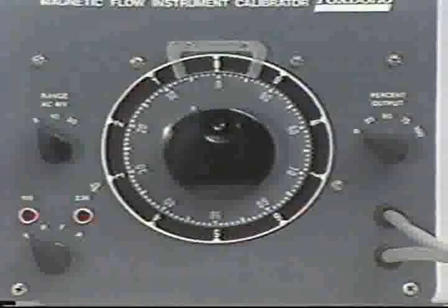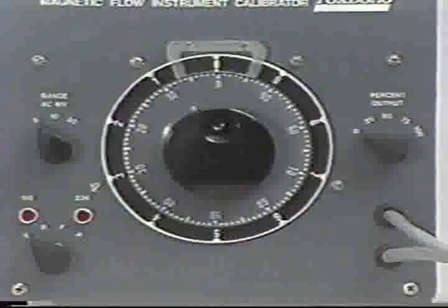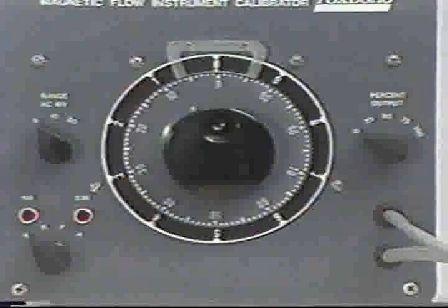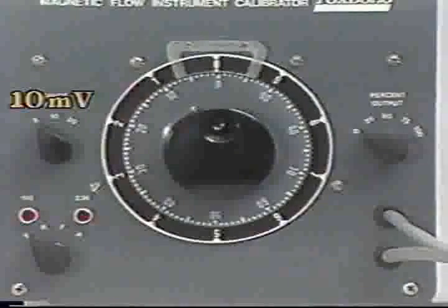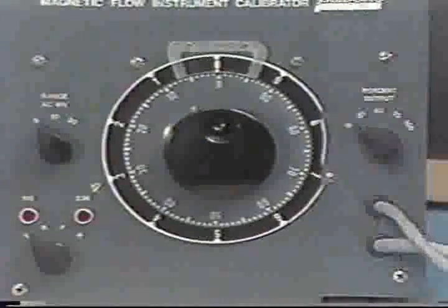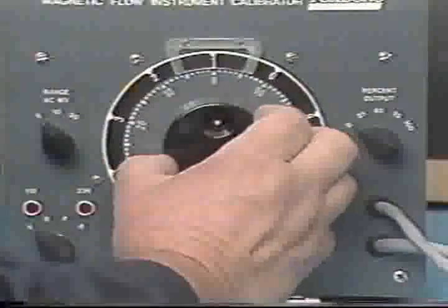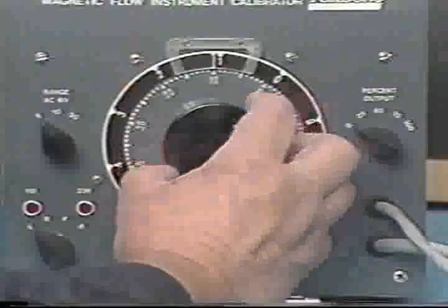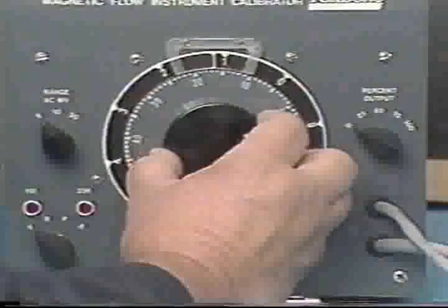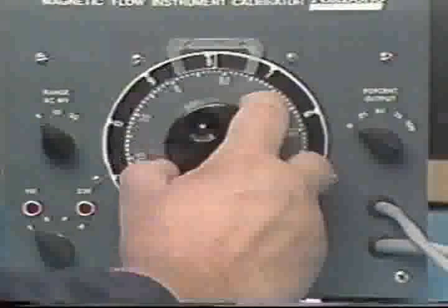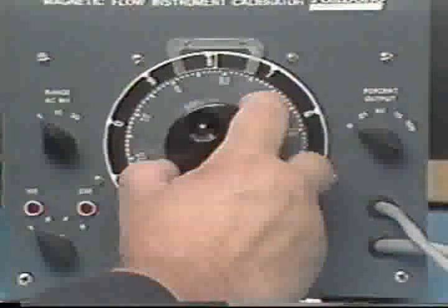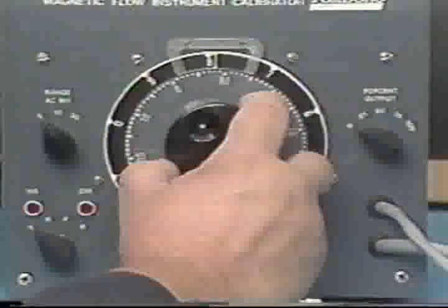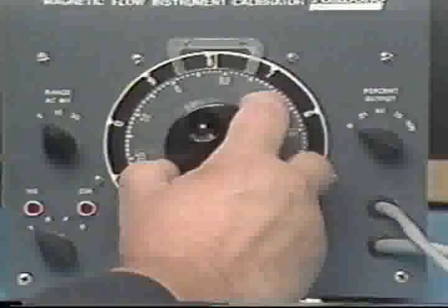Now, set the calibrator's range knob to select the maximum output signal. This is the smallest value which includes the calibration input signal. For this example, then, the range knob should be set to 10 millivolts. Remember, the input signal is set through the turns counting dial. The outer portion of the dial indicates the whole number millivolt value. The inner portion indicates the decimal millivolt value. The turns counting dial here is properly set for the input signal value for this example. The outer dial is set on 7 and the inner dial at 92.